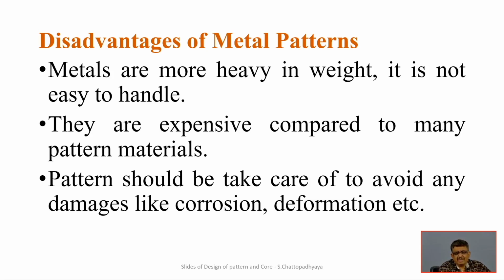Previously wood was less expensive, now woods are becoming more and more expensive. But metallic patterns in earlier days were very expensive, and if you want rust free metals and all those things, then they are really expensive. Then the pattern should be taken care of to avoid any damages like corrosion and deformation. These kinds of surface phenomena will challenge the dimensional integrity of a pattern. So corrosion and deformation have to be critically monitored.